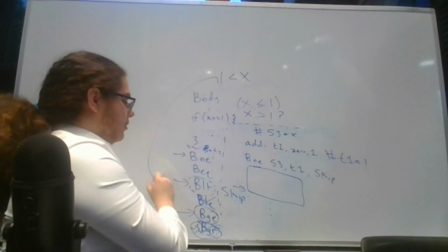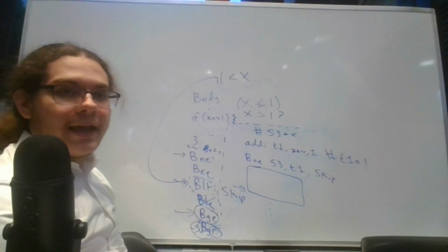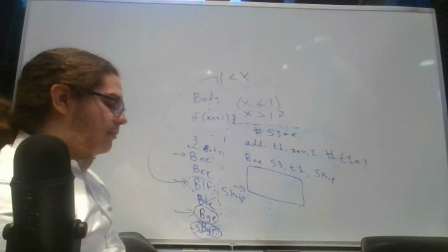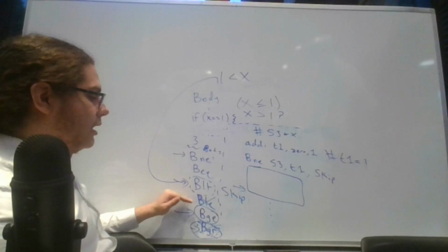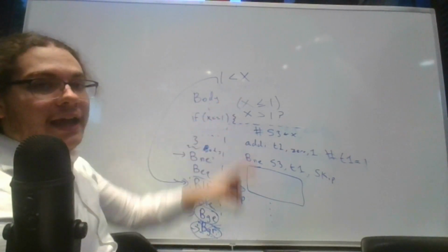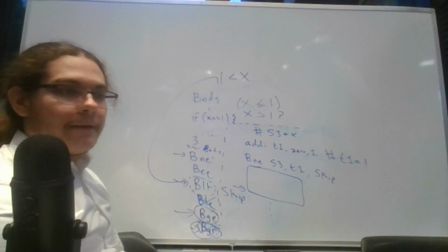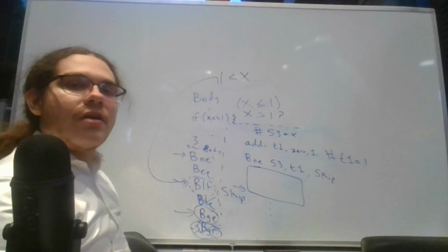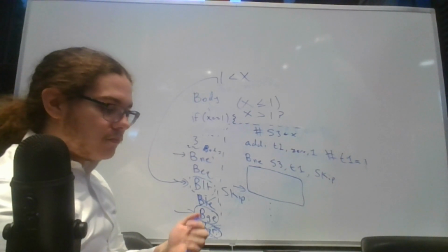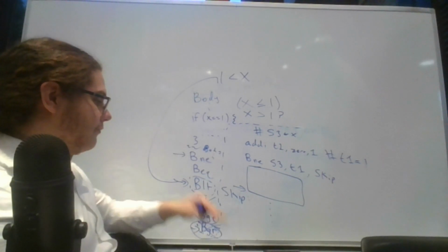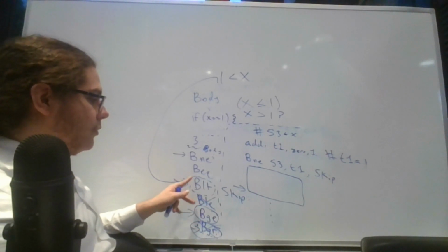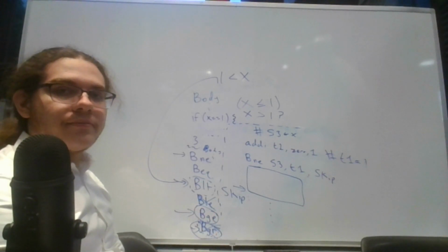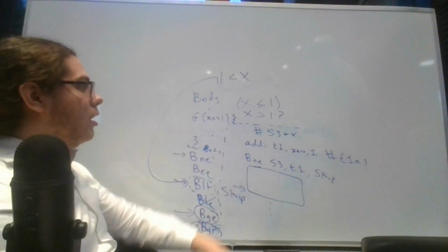But if you look, less than is a real instruction we have. And so the reason why we have these pseudo instructions and why we can decompose them is because firstly, we have them so that we can easily write these things without having to switch stuff in our head. It makes it easier for us to type. But secondly, the reason why we wouldn't just implement all 4 is because that saves us on processor hardware. So we don't have to implement 4 different hardwares to do each of these. We just need 2 of them, and we can implement the other 2 in terms of the ones we already have. And that works for the other one as well.